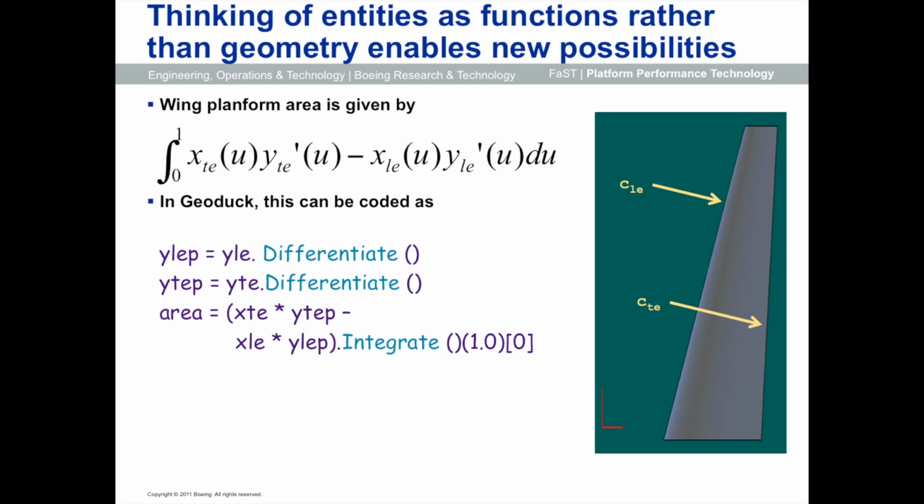So the wing planform area calculation, if you look at this in the Boeing design guide, will be a discussion that goes on for 6 or 8 pages. If your wing is a trapezoid, use this formula. If you have 1 break in the leading edge of the wing, then think of it this way and use this formula. Nowhere in those 6 or 8 pages does this integral, which tells you what the wing planform area actually is, appear. But you can write it down. You can figure that whole thing out.